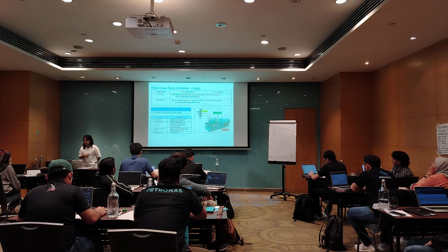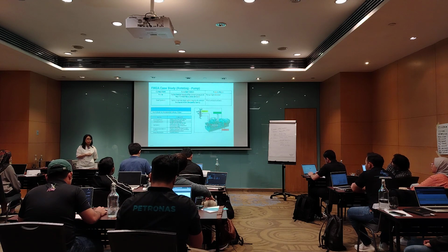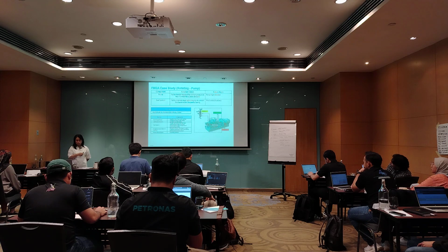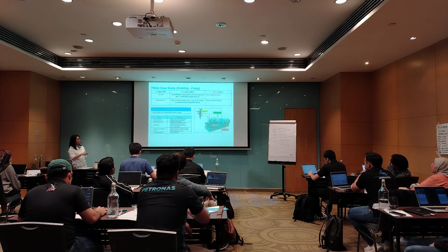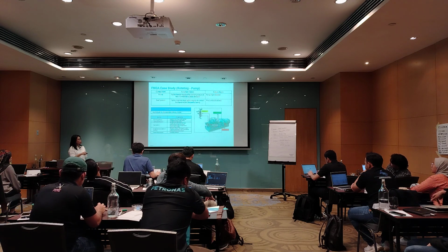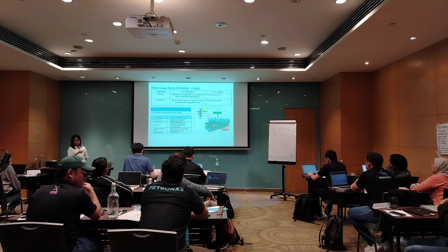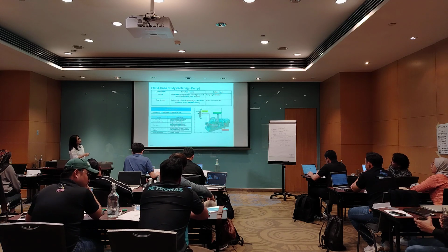So the failure mode is high vibration. Second, the seal system: fail to maintain leak-tight integrity. So mechanical seal leak. You guys also mentioned that in the failure modes. So this is the tagging. Since these are the operating parameters, and then a component inside it, this is the equipment boundary. Alright. Next.